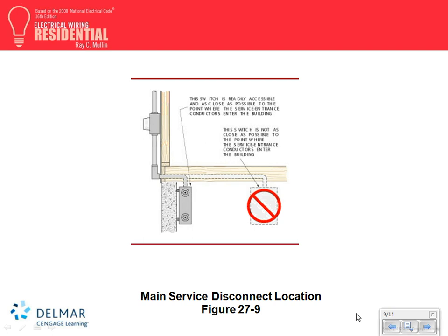Another thing I want to bring to your attention, guys, service entrance conductors. Since they're not protected, you have to put them right at the point of entering the building. So the minute that you enter the building, every time, you have to put your service entrance conductors. Meaning, can I bring that service entrance panel here and put it in an inside wall if I can't put it in an outside wall? No. The code says the nearest point of entering the building.